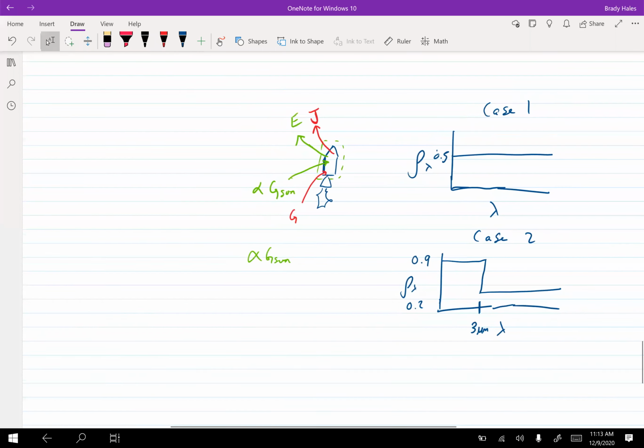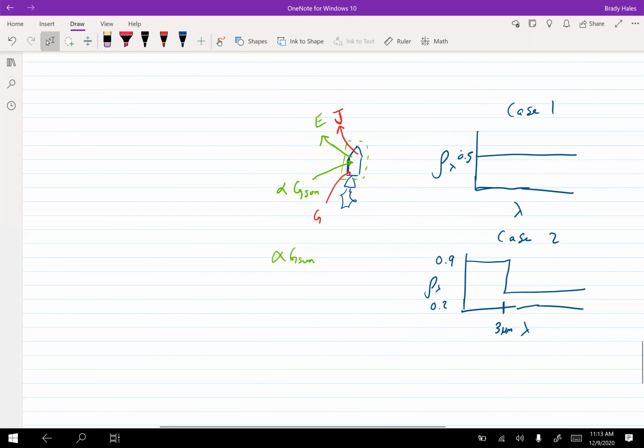Okay, so first off, let's draw out our energy balance. So we have alpha G sun minus emissive power of the rocket. And then technically both of those are multiplied by A. This is minus E, A equals 0.